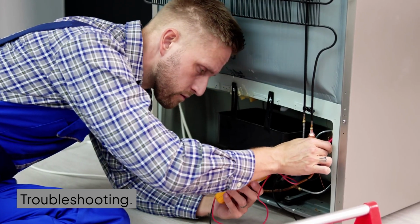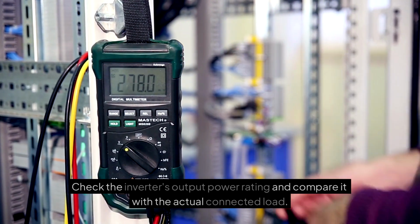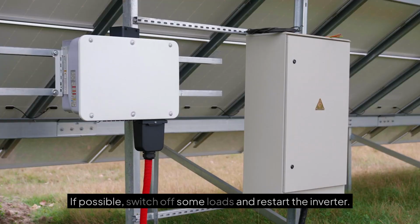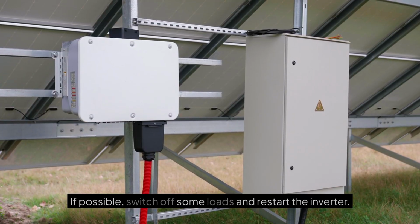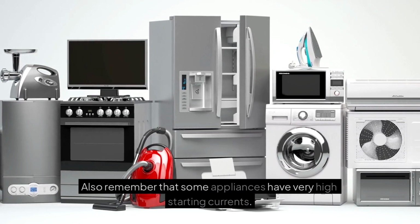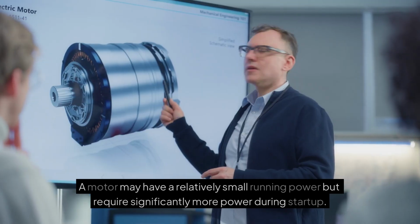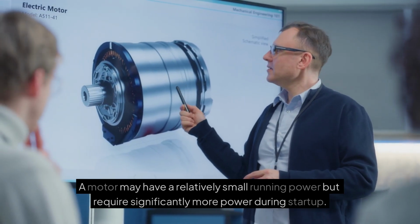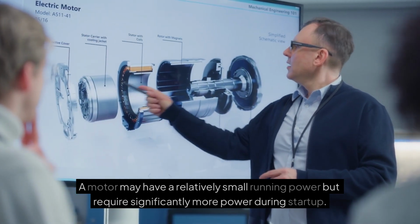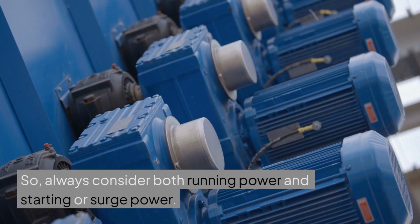Troubleshooting. Check the inverter's output power rating and compare it with the actual connected load. If possible, switch off some loads and restart the inverter. Also remember that some appliances have very high starting currents. A motor may have a relatively small running power but require significantly more power during startup. So, always consider both running power and starting or surge power.